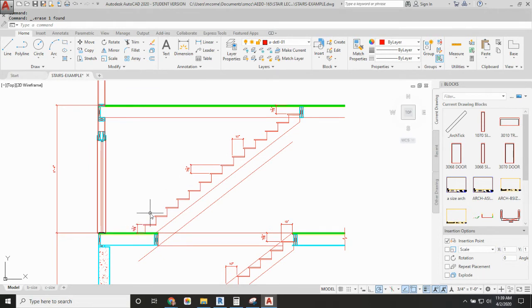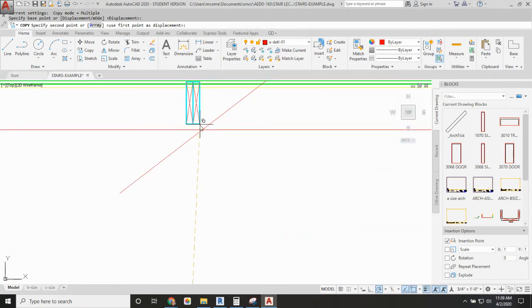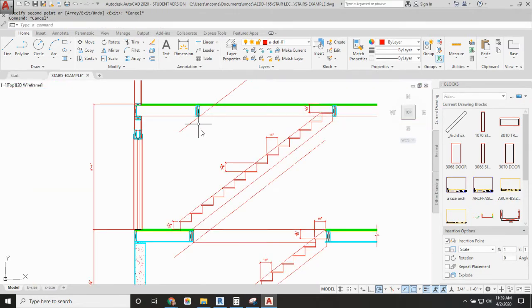And let's test the theory because this is 15 risers. I'm going to draw a line from nosing to nosing all the way up. And this I'm going to copy, not offset, up 6 feet 8 inches. And this shows us where we have to put our opening for our stairs. Somewhere around there, given the fact you're going to have some finishes and stuff. And then let's look to see where that happens over that second riser, tread rather.